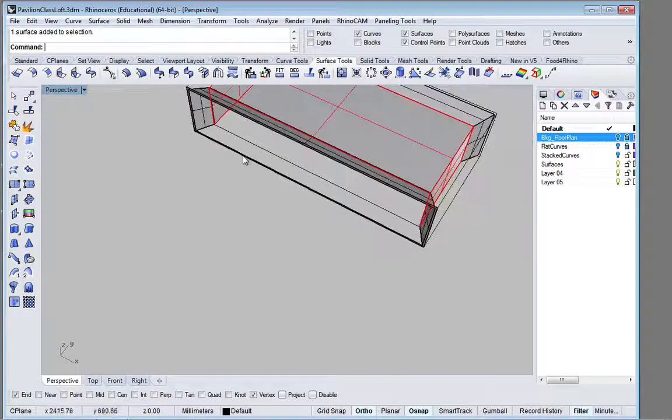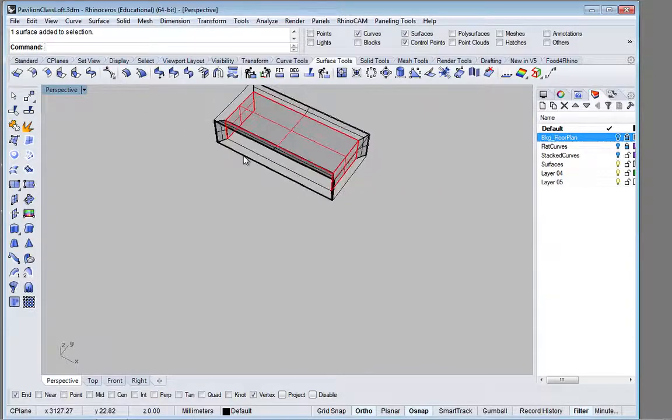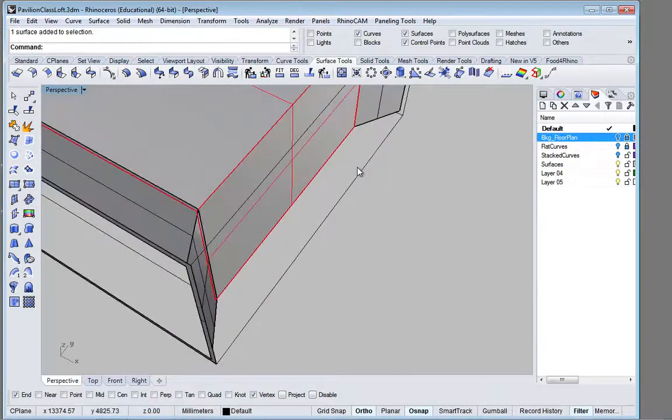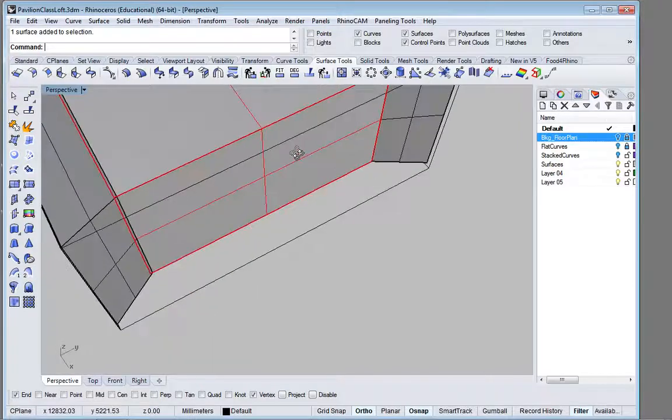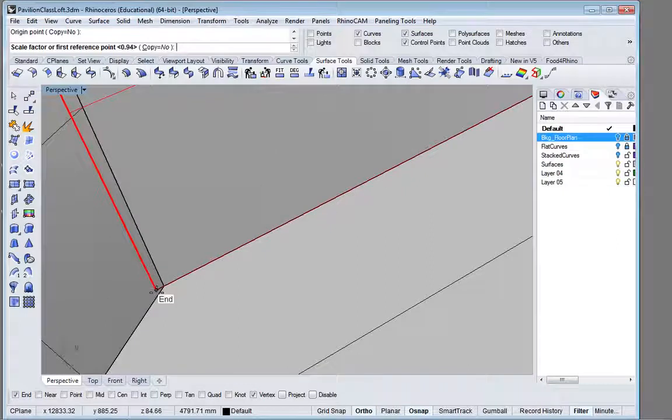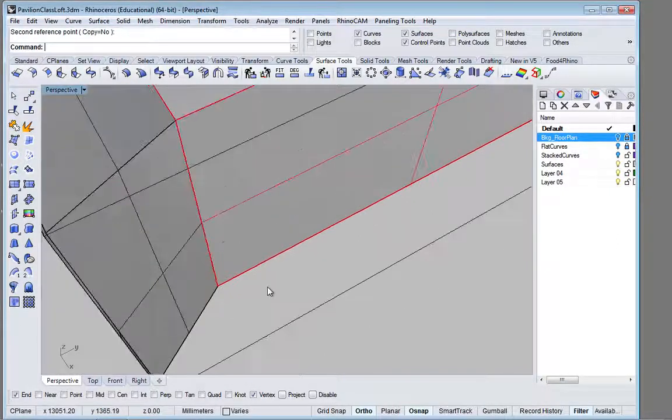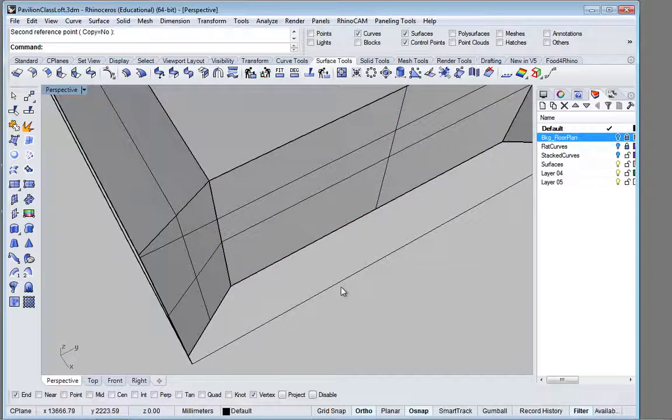And our handy scale 1D tool will come in handy again. So I'll type scale 1D. And I'm going to select this corner here. I'm going to zoom in, select that corner, and then just snap it back to that. And now we're back. Everything is kosher.